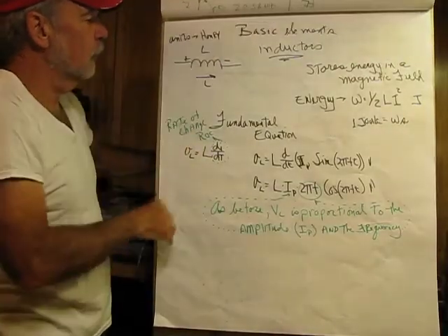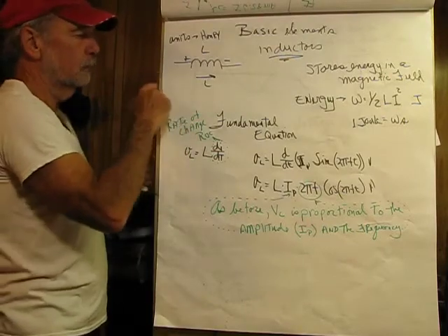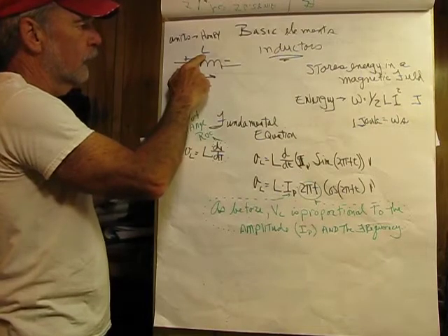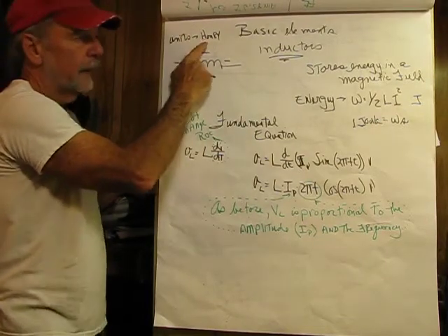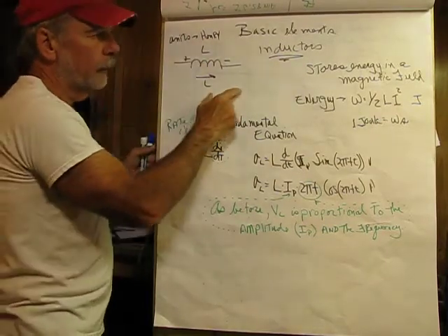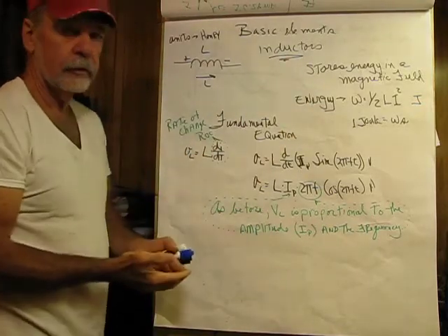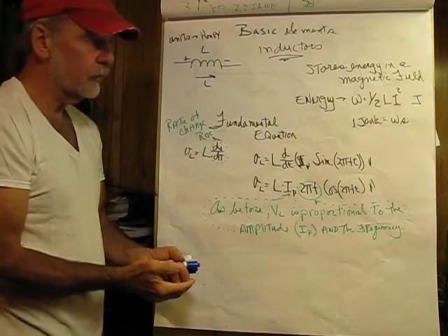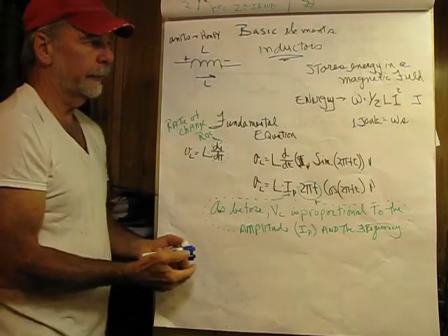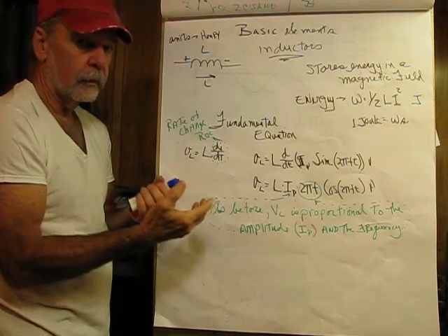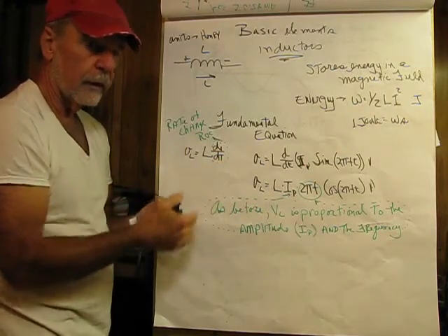Our next basic element is the inductor L, passive current convention, plus the minus, current flowing in this direction. Here's L. The unit is the Henry, capital H. And an inductor stores energy in a magnetic field, and this is kinetic energy, whereas a capacitor stores potential energy. So basically, the current flow produces a magnetic field, and when you interrupt the current flow, the magnetic field collapses.